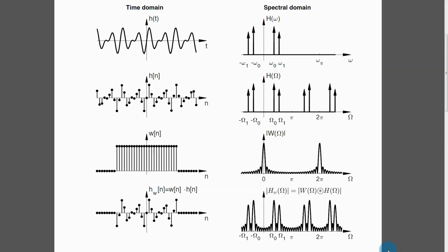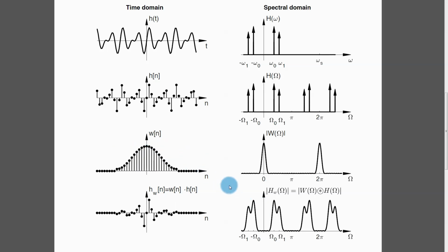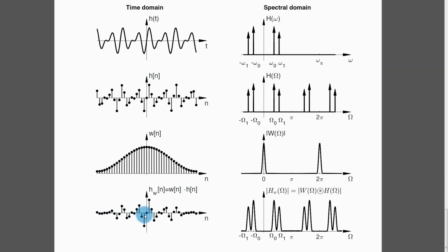Now, just to finish, this is a very ugly spectrum, full of spectral leakage. So to get rid of that spectral leakage, I will change this rectangular window to a nice smooth one. Now I have much less spectral leakage, but the spectral resolution is not exactly fantastic. The problem is that this smoother window has wider peak in its spectrum. So to get back the spectral resolution, I have to use even longer signal. And when I do that, I will get a spectrum I do not have to be ashamed of.